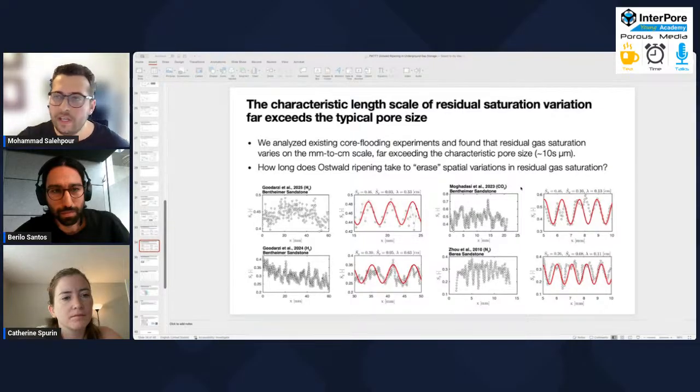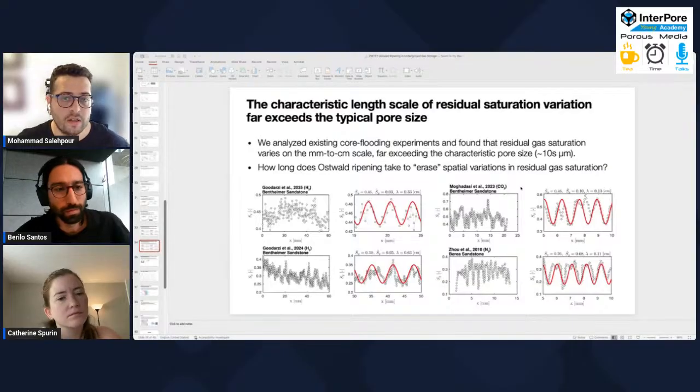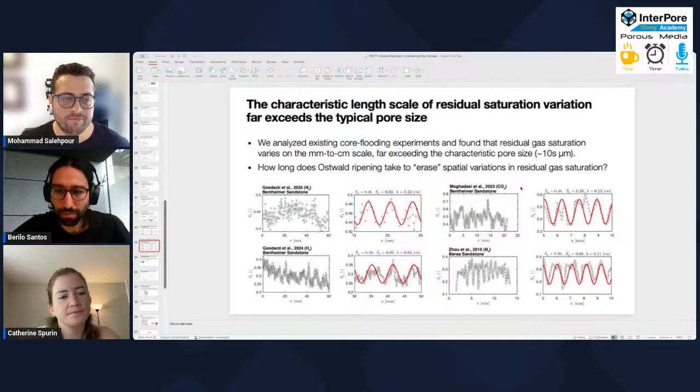Yeah, I think using the PNM code, we are able to extract the correlation between the saturation of the trapped gas and also the capillary pressure. This capillary pressure is based on the heterogeneity of this porous media, which is how well the pores are connected to each other, how long the throats are, and all of that. So I think that is incorporated into the 1D model that we developed, which looks at how pores are distributed and what the heterogeneity of the system is. Interesting. Great. Thank you. Thanks.